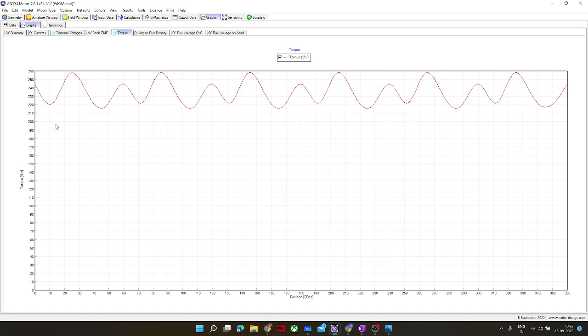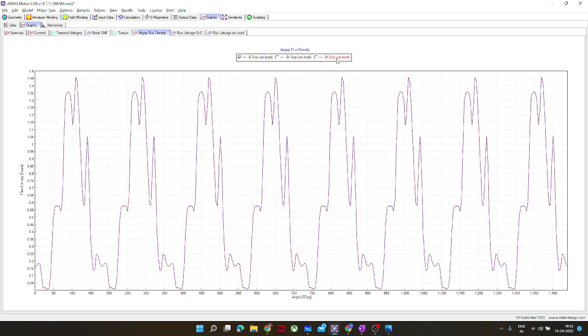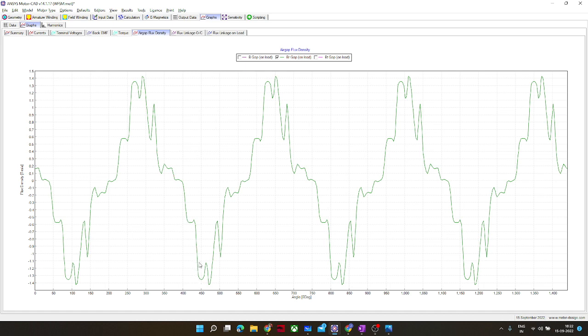Many people do research in reducing this component. So this is how your air gap flux density varies. It is also expected to be sinusoidal, not this one, this one. But there are stator and rotor teeth. In a pure cylindrical, toothless machine, there will be pure sinusoidal, but here the air gap is not uniform, so you would not get uniform air gap flux density.